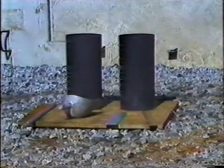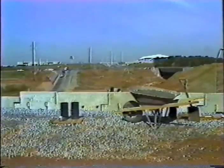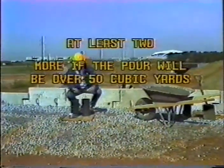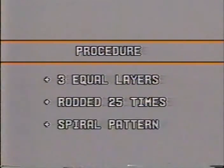As part of the preparations, make sure there are enough cylinder molds on hand. You will need to make at least 2, and more if the pour will be over 50 cubic yards. The procedure for casting cylinders is very much the same as the slump test. 3 equal layers of concrete, rodded 25 times in the same spiral pattern.